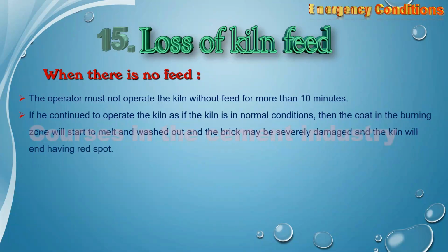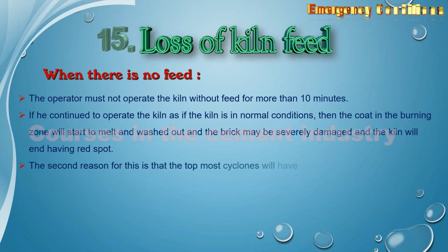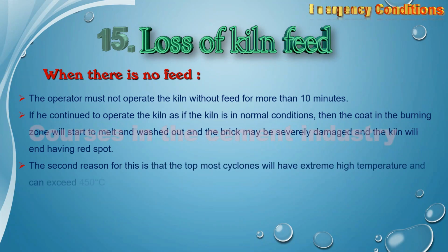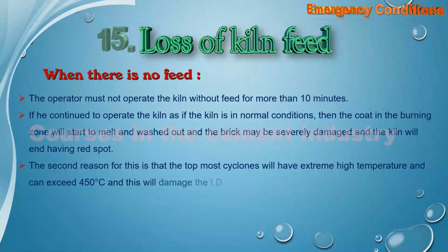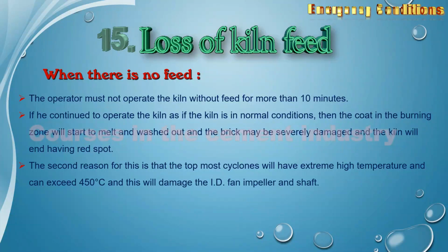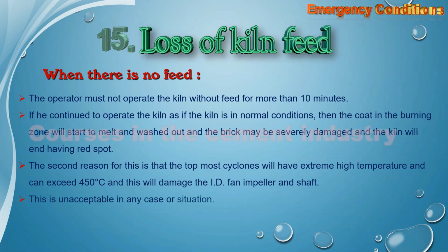3. The second reason for this is that the top most cyclones will have extremely high temperature and can exceed 450 degrees C, and this will damage the ID fan impeller and shaft. This is unacceptable in any case or situation.